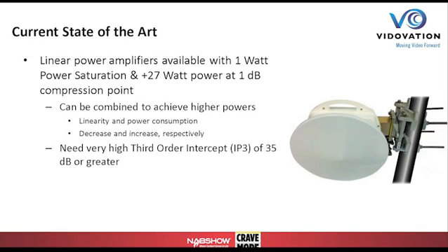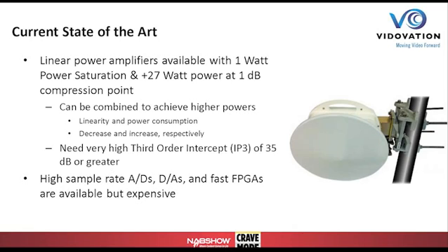But it's not just crude amplification. We need amplifiers that don't have distortion or third order intercept issues or intermodulation issues. It's got to be clean signals. So if the signals are distorted during amplification, that limits our transmission capability.